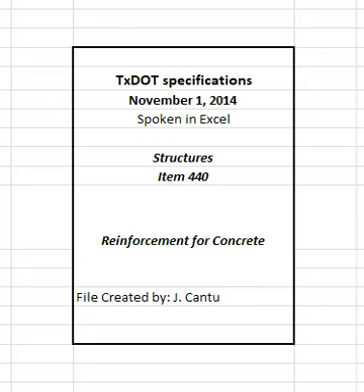Clean the steel of oil, grease, moisture, dirt, welding contamination, slag or acid residue, and rust to a near white finish after welding or coupling. Check the existing epoxy for damage. Remove any damaged or loose epoxy back to sound epoxy coating. Coat the splice area after cleaning with epoxy repair material to a thickness of 7 to 17 mils after curing. Apply a second application of repair material to the bar and coupler interface to ensure complete sealing of the joint.